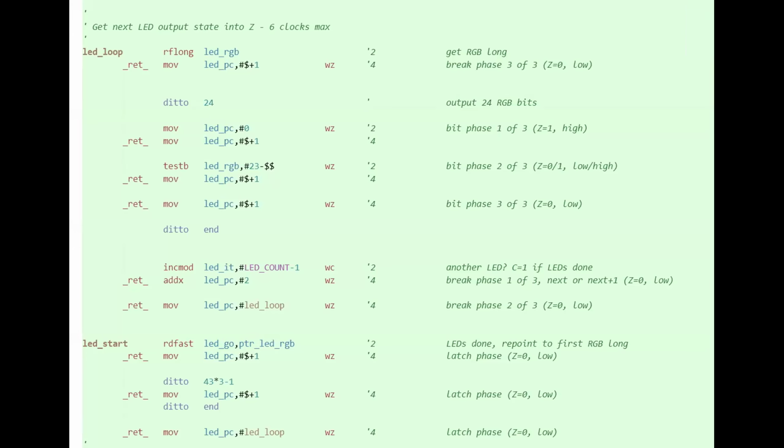But the only thing about that tracking thing, it sounds like if it did track, then I'm not sure it's recoverable on the PCB. You mean the arc thing? Yeah, because that's going to create a carbon track, right? So you have to dig it out. It could, yeah. But here's the thing. Normally these signals are like 0 to 24 volts, so a carbon track's not going to be very conductive at those lower voltages.